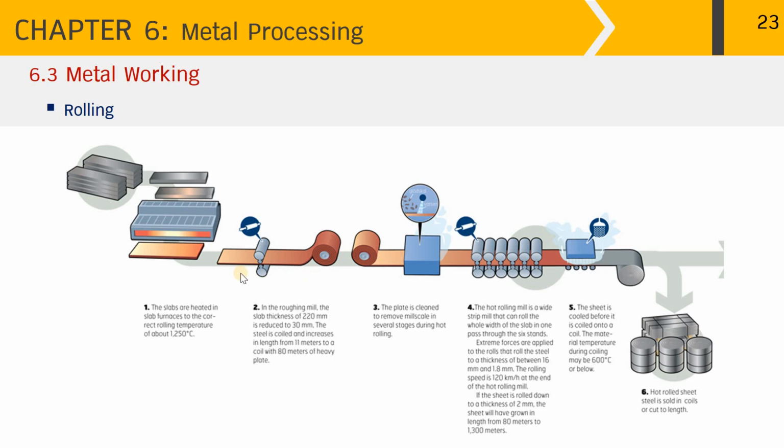And next, the slab will be going through the roughing mill, as you can see from the roll stand over here. The working rolls are on the top and the bottom, and the backing roll supports the working rolls. This set of the rolls is called a stand.